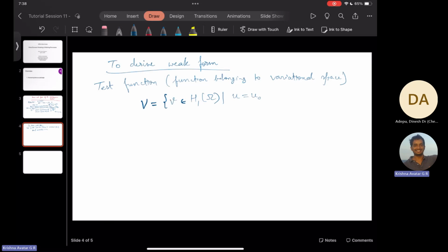I'll just call it V so as not to confuse you. This is like V equal to 0 for all x, since this is a vector. So V is equal to 0 for all x in omega, and there won't be any mention of t. So we always take test functions to be virtual. These are essentially virtual displacements. As we recall, virtual displacements do not depend on time because they are taken at one particular instant. We are giving some virtual displacement to a system.